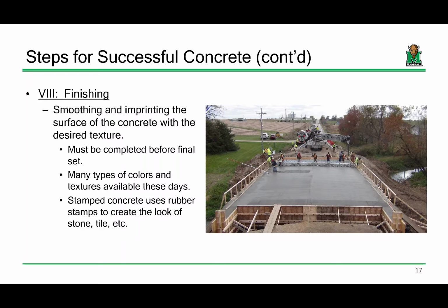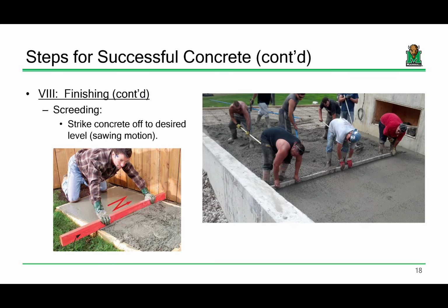Water, right? When rain hits, or when water hits the top of the bridge, we want the water to drain off. If the bridge is just flat, the water's going to sit there, and that's no good. We want it to drain off. So the cross-section of the bridge has to have a little bit of a crown. And so what that is doing is creating that crown, okay? So it's not flat, okay?